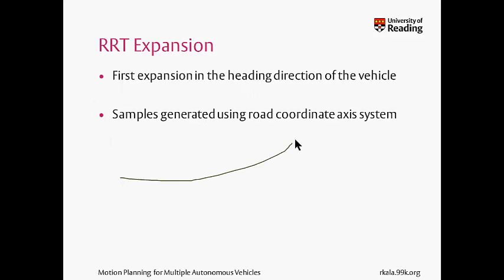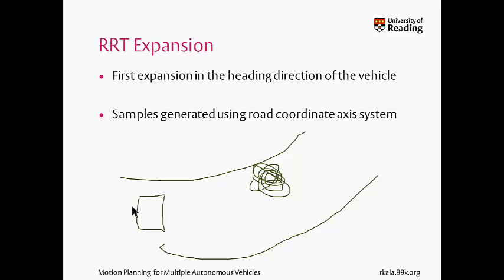I have been given some kind of road like this, which has some obstacle. Say here, there is a vehicle which is the source. The second thing I need to do is the goal. I said goal is any point out here. Unlike some other approaches, RRT does not need a very clear definition of a goal, so I can say that the goal is any of the points out over here, or there are multiple goals, any one of which can be reached.